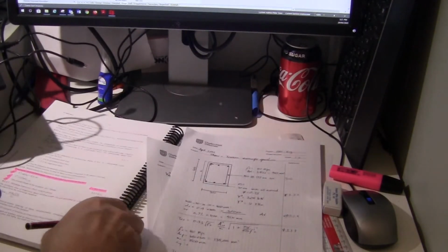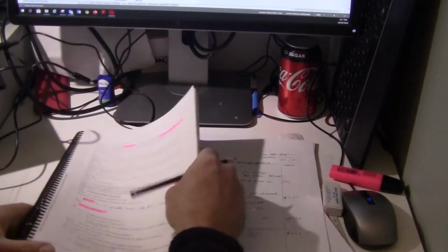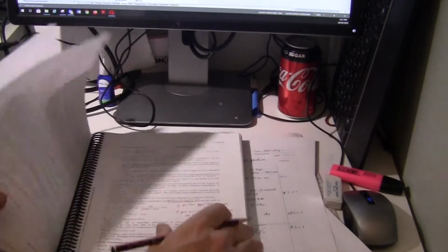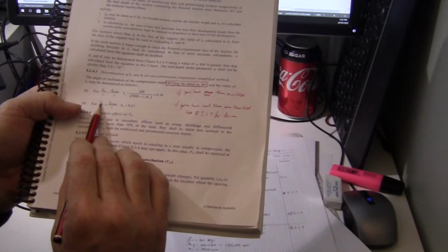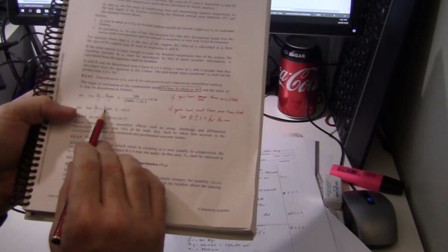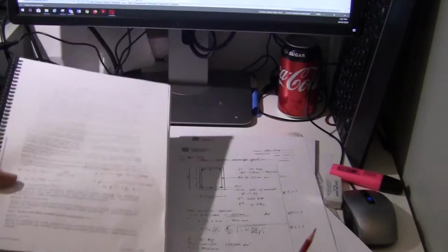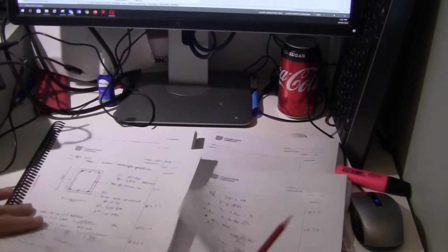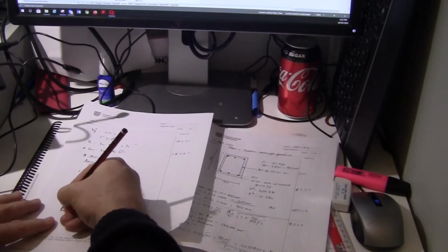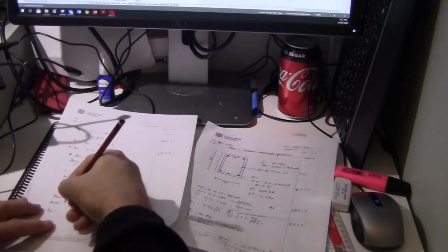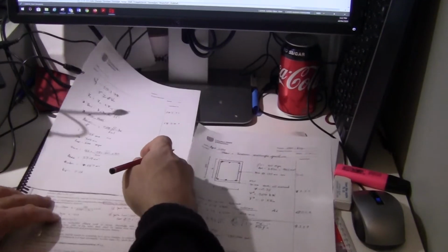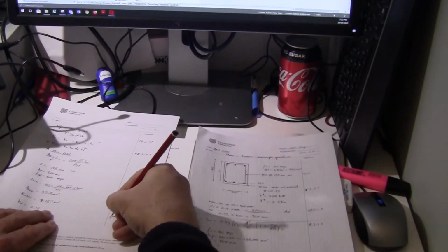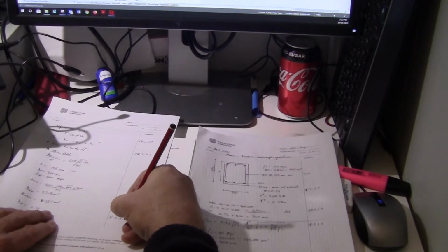So now we're going to go back to over here. So our simplified thing here, we're going to find KV. Our steel is greater than the amount of minimum steel, so our KV value is 0.15. That was a long detour, wasn't it? KV equals 0.15, and that comes from clause 8.2.4.3.